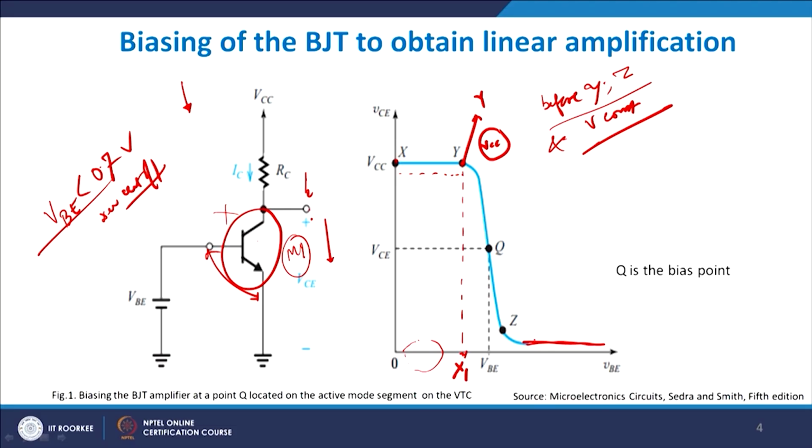Now, you see we define the Q point, quiescent point, as Q, quiescent being a point which is highly stable, right. So, these two are the definitions of the Q point which is seen in front of you, and which means that this Q point by application of an external bias can move up and down, but within the linear regions of amplification process, right, and you should be very careful as far as designing is concerned, that you cannot let the Q move anywhere it likes, but only across the small signal domain, such that you get a large amplification in this area.